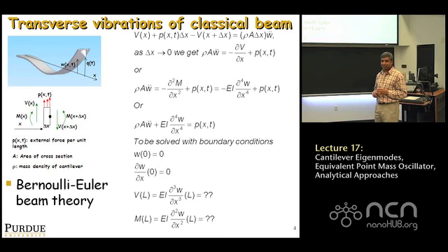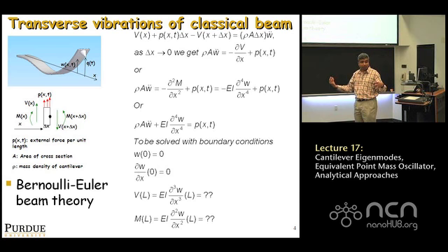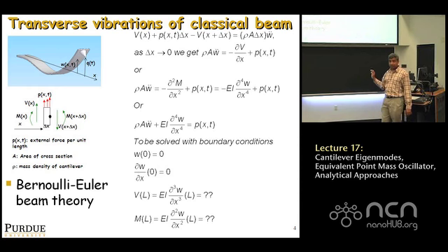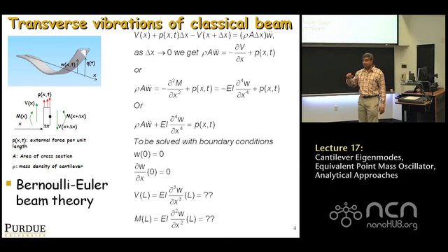It is a slightly tricky question because after all, this entire equation of motion I wrote down was for the beam, not for the tip, right? So if we want to include the effect of the tip, it would have to come into the boundary conditions at x equal to L, right? Because so far the equation is just for a beam, not for a little sharp conical tip at the end. So if you just set this equal to 0 on the right-hand side, you're basically saying that the mass of the tip is negligible, right?